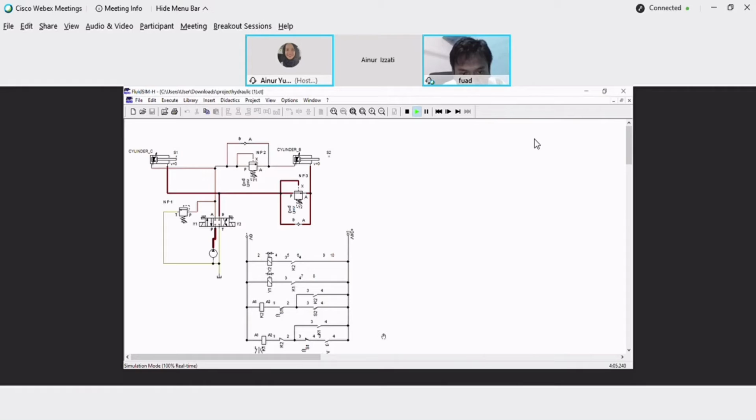For this project, an electrical actuation of a 4/3-way solenoid valve with shut-off position has been developed. There were two double-acting cylinders used in this electrical actuation system, cylinder B and C. Indirect actuation has been used for these cylinders. The current only passes into a relay coil for indirect actuation while the main switch is pressed. The solenoid is energized by this effect, which then changes the position of the 4/3-way solenoid valve with shut-off position. After the direction of the solenoid valve changes, the fluid shifts according to the direction of the solenoid valve.